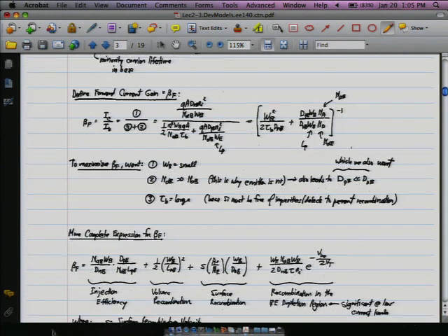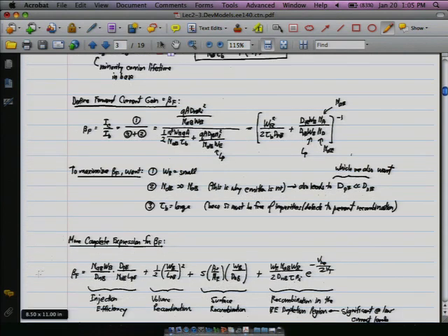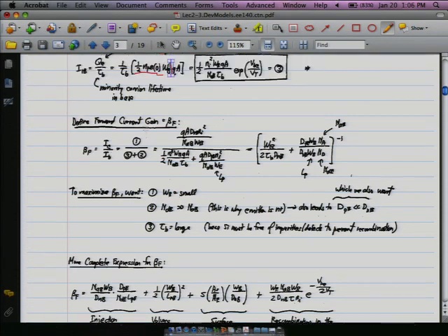the most important factor that we're looking at most of the time on BJTs is the forward current gain. And sometimes we'll see this as beta F. Sometimes it's just beta. It's the same thing. In SPICE, I think it's just capital B, capital F. So this basically is a ratio of the collector current to the base current. And so that, from the equations we had before, is equation 1 divided by equation 3 plus equation 2.